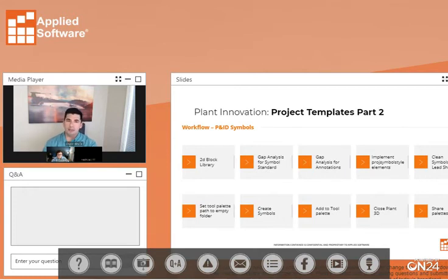And then the same thing needs to be done for your annotation. In order to move away from fully text or MText based annotations, we want to make those intelligent. So we would take some sample drawings, it might be 5 or 6 or 7. We don't need to look at all 1,000 of your P&ID drawings, but pick a sample set and go through and see what you are calling out on a regular basis. There will still be some instances where you're just using text, but our goal is, if there's a tagged item or a property coming from the data of your objects, we want that information to be driven from your annotations.